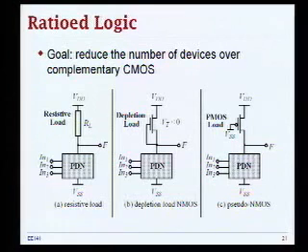What happens with the noise margin in this case? What is the VOL equal to? What is the fundamental problem? The fundamental problem is that this one never turns off. So when you're pulling down, normally in complementary CMOS, you have your pull-up disconnected. And you're happy pulling down. But now you have this guy working against you.